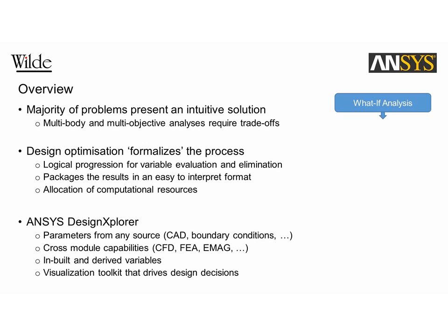The general steps are, we start with a what-if analysis. This is our best guess. This is our initial optimization. It's a manual optimization. We then move to correlation studies, where we assess what actually matters to the analysis and to our output. We run a set of design of experiment studies, where we take the parameters that matter and bind them within a design space.